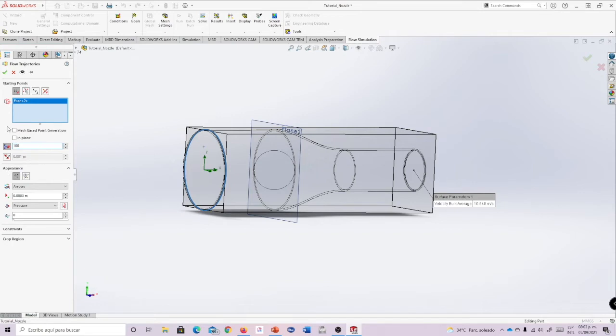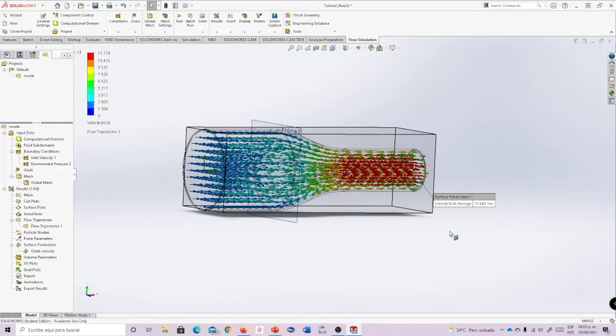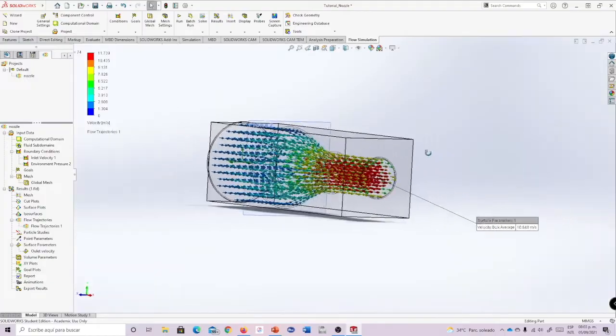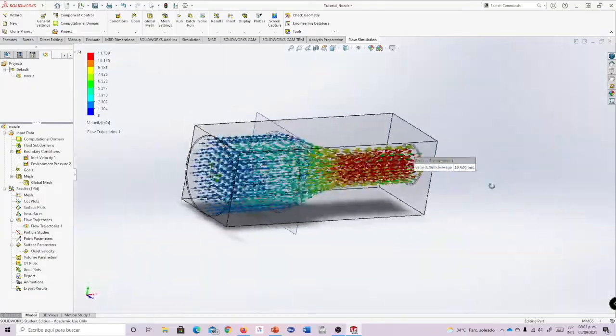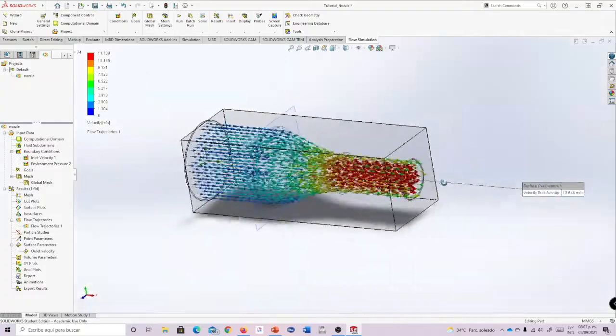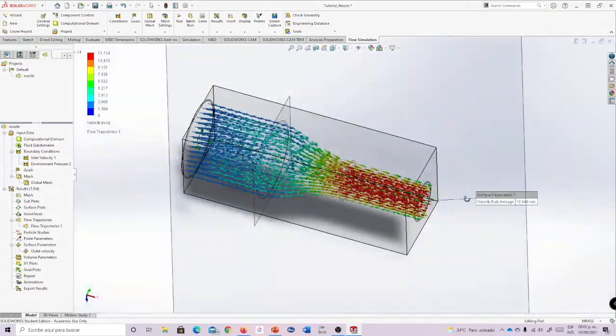100 elements, and the elements will be arrows, and we can select here the variable we want to show in this profile. The problem says that is velocity, but you can select any property you want to show. It will be velocity. Okay, I'm gonna click OK, and there you have. This is a static image or graphic, but you can have this image